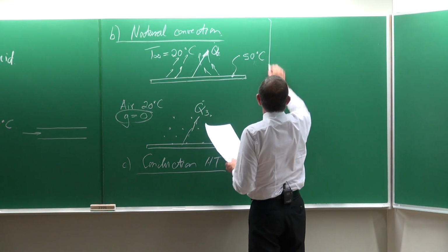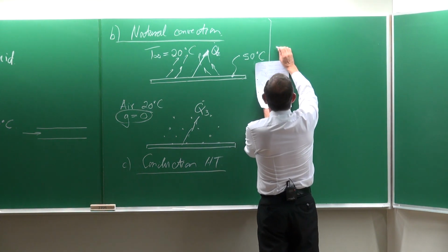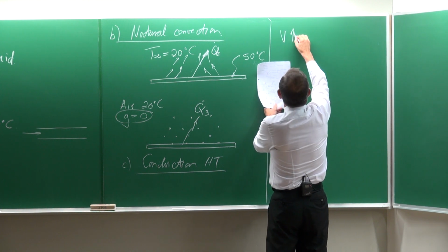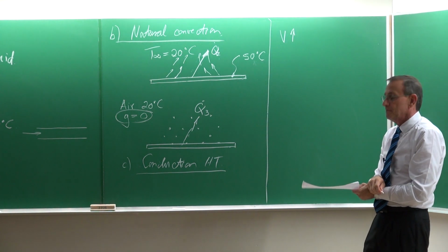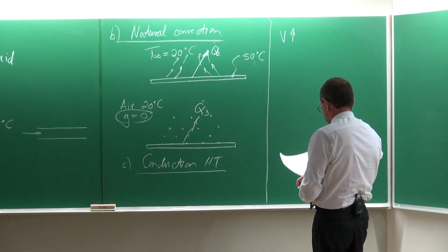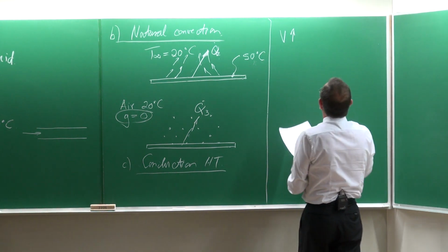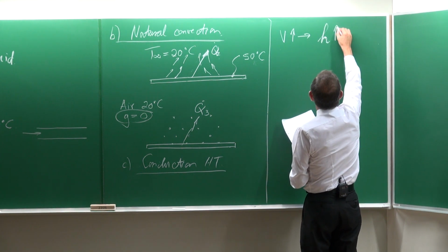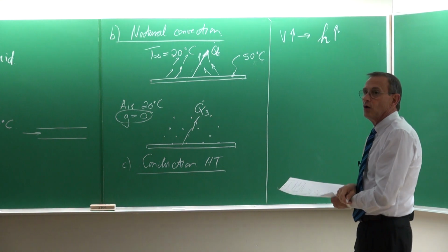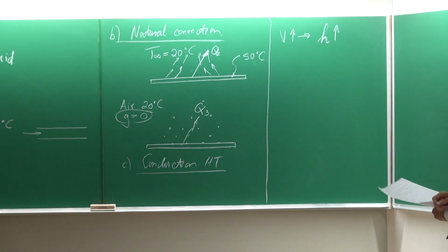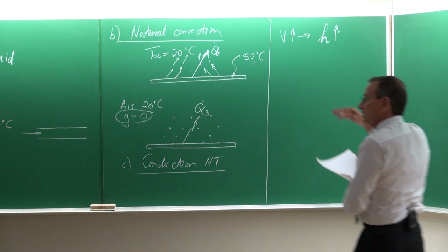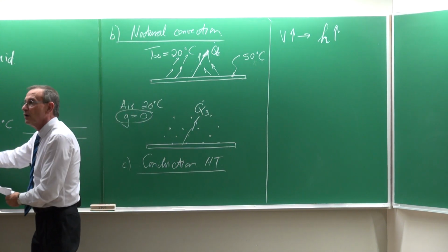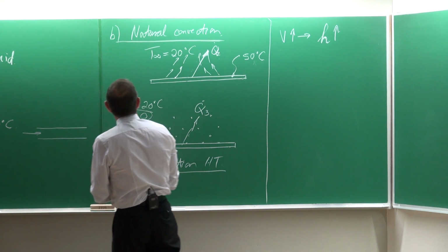Now, in general, the higher the fluid velocity will be, the heat transfer coefficient increases, or the heat transfer rate is going to increase in general. So if we think of this velocity, the higher that velocity will be, the more heat can be transferred.